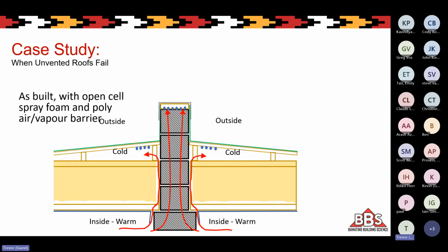Basically what happened is when they replaced the closed cell spray foam with open cell spray foam, they added a polyethylene vapor barrier, but it wasn't sealed properly at each of these demising walls. And there was a lot of air leakage occurring through there. There's also a lot occurring through these block demising walls. And so what happened was we ended up with a lot of moisture accumulation in the sloped area of this roof and up in these parapet caps. So what did that look like?